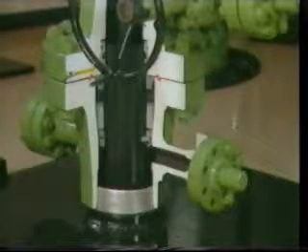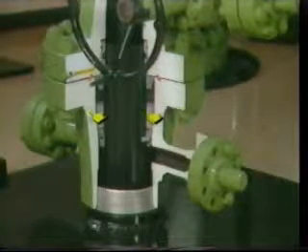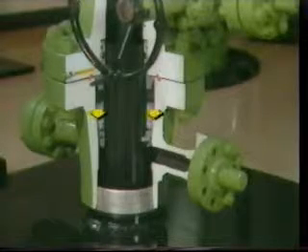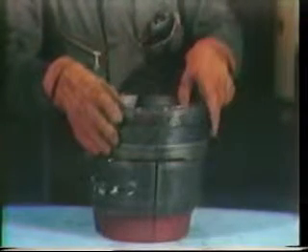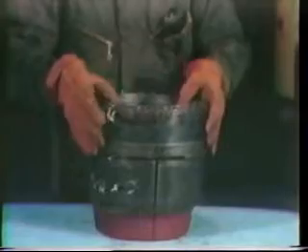The casing hanger's primary purpose is to transfer the weight of the casing string to the casing head or spool. There are two generally accepted types of casing hangers: the more common slip-type hangers and the mandrel-type hangers. Slip-type hangers, sometimes referred to as wraparounds, have a tapered back that matches the taper on the inside of the slip bowl.